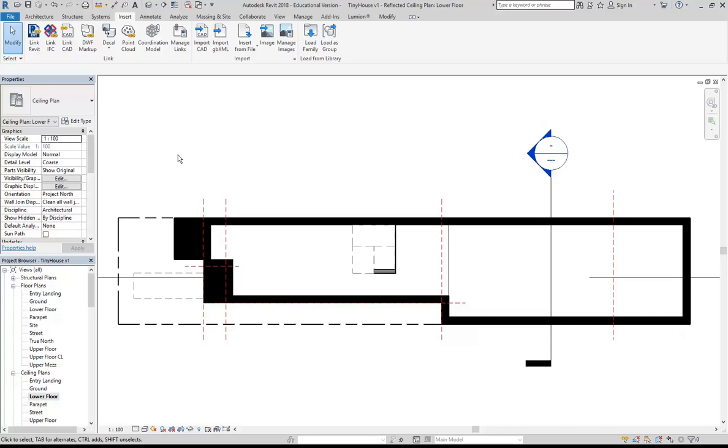Have you dealt with cut planes before? So do you know what height a floor plan usually has the cut plane? So, yeah. About that. Well, if that's for ceiling plans, that would be about right. So for floor plans, yeah, between 1 metre and 1500 is pretty standard. And then ceiling plans usually are higher.